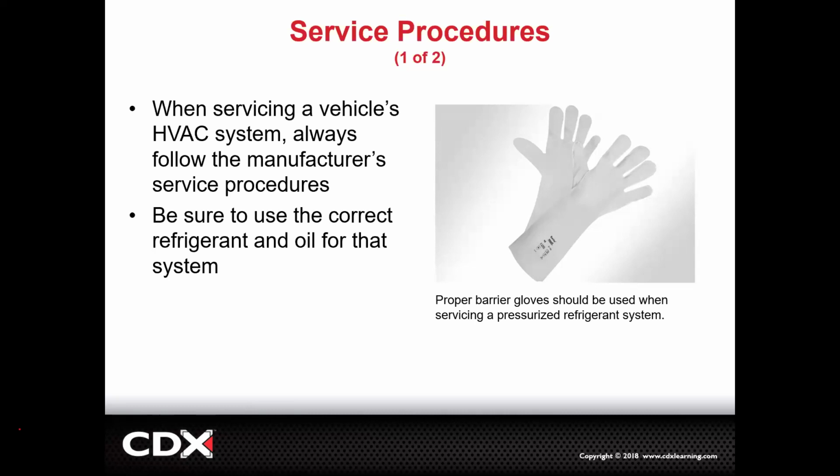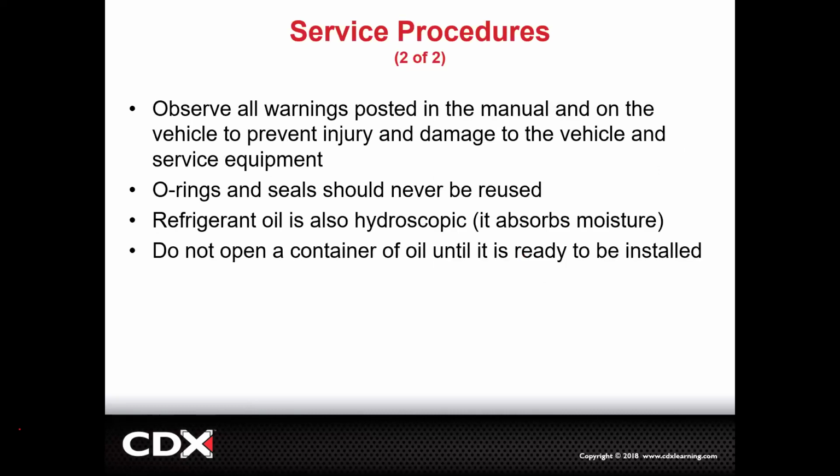Cool. But again, before you service the AC system, check the manual. A lot of times they'll have some warnings and some hazards and some details to make sure you know kind of what you're getting into. Also, we shouldn't really be reusing O-rings.